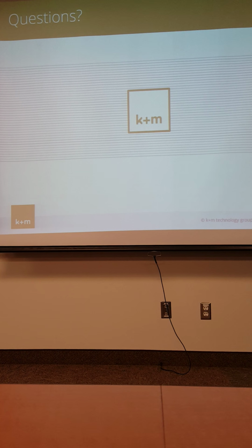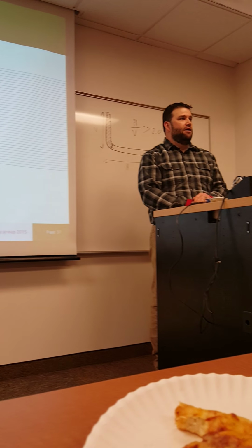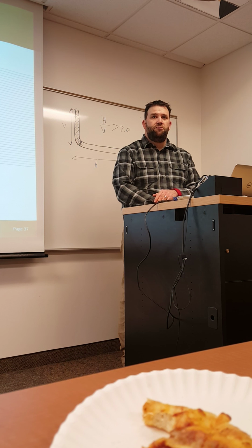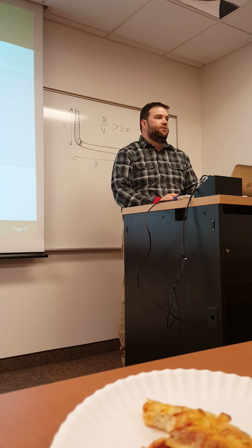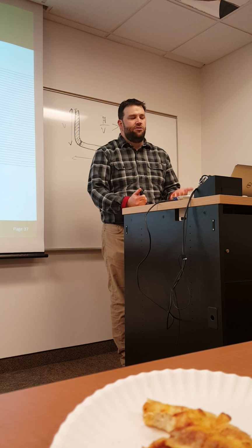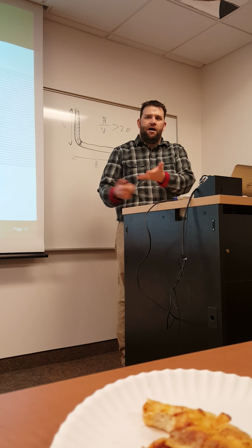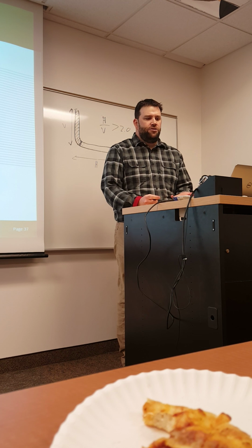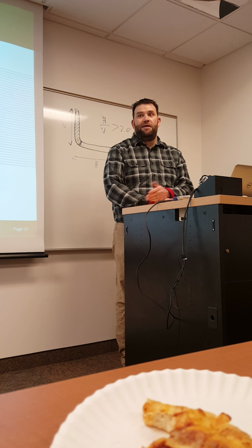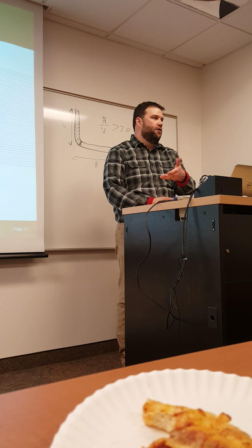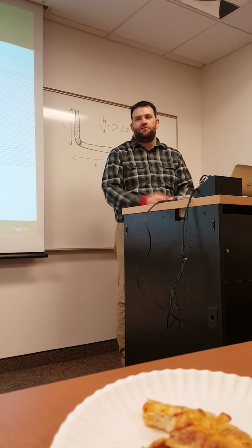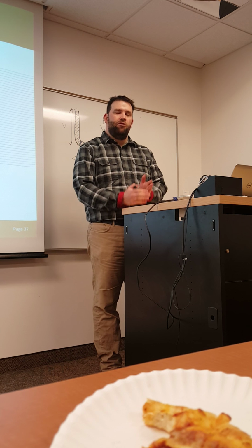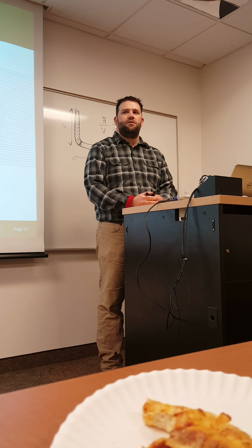So water is a great drilling fluid because you get turbulence almost the minute that you touch the rheostat for the pumps, because at very low flow rate, water's in turbulent flow, and that turbulent action stirs up a lot of material. But in most places, you need higher density in order to combat the pressures of the rock, higher than 8.33 pounds per gallon. And so in order to get the density up, we have to add stuff like barite, and the barite won't stay in suspension in water, so we have to put viscosifiers in there, and the viscosifiers break us into laminar flow. So water or brine, if we can drill with clear fluids, turbulent flow works all day long.